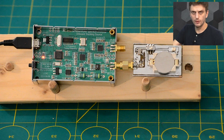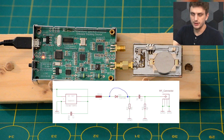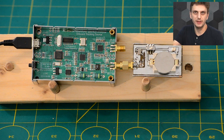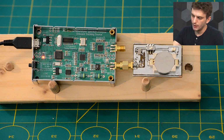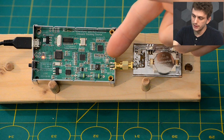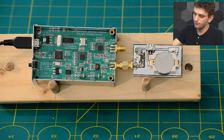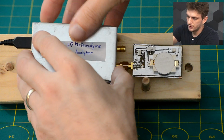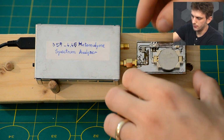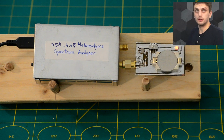So first things first, I short-circuited my diode so that we can see the spectrum of the signal that we're starting off with. No point in making a complicated circuit if you already have enough harmonics. And I have this connected directly to the input of the spectrum analyzer. No extra resistors were added this time because the spectrum analyzer already has a 50 ohm input. So cover this thing up to prevent any extra noise getting in, and let's see what the spectrum looks like.